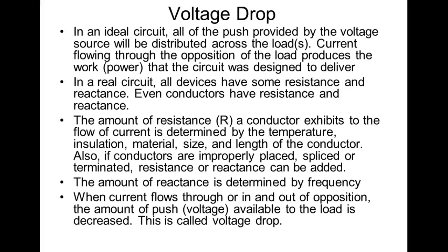And the problem is if we have a lot of voltage drop, remember, power varies with the square of the voltage. So if the voltage halves, then you're going to be able to deliver only 1/4 of the power that the load needs. So I either got to do what? I got to figure out what material I need to use, and then I got to make sure I use the right size for the watt. The length that conductor is going to have to run. And then I've got to determine how much current that guy can handle depending on what temperature it's designed to run.